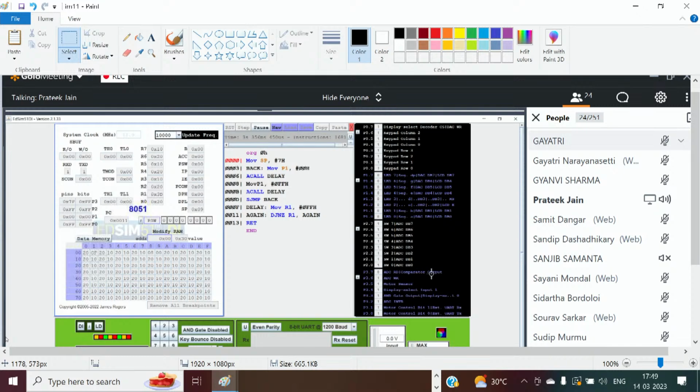For this we apply the command DJNZ R7, $. If it is decrementing the value to 0, it needs a value to jump to, and this is the dollar.